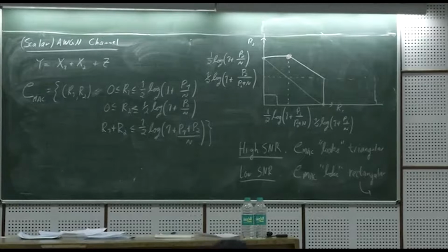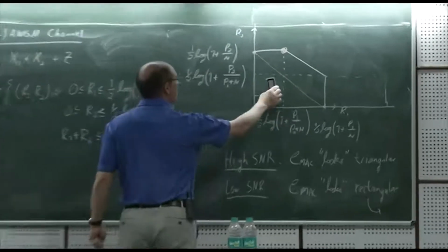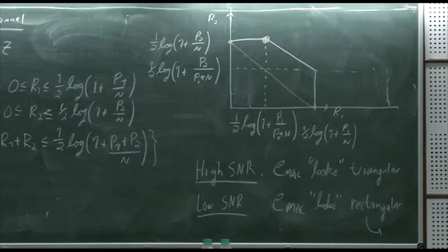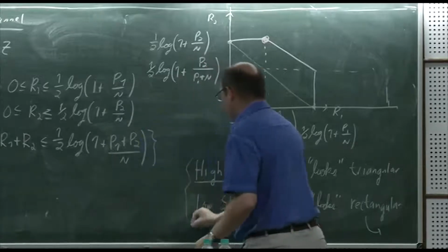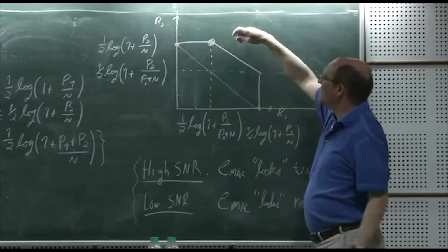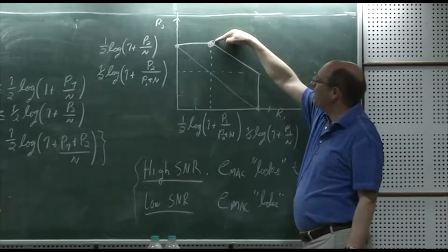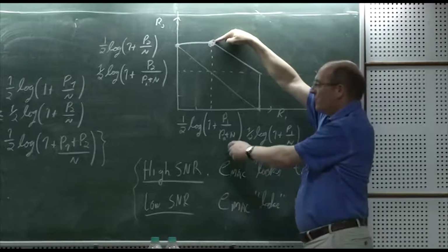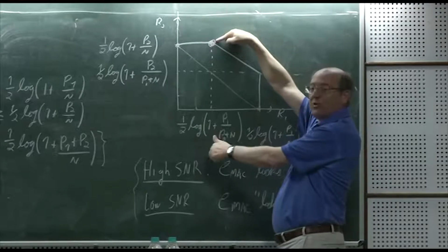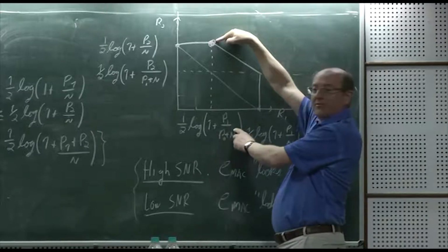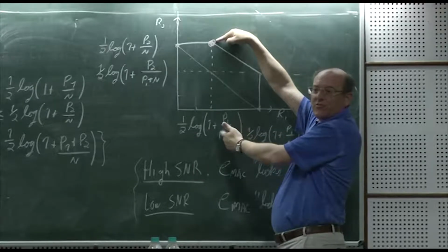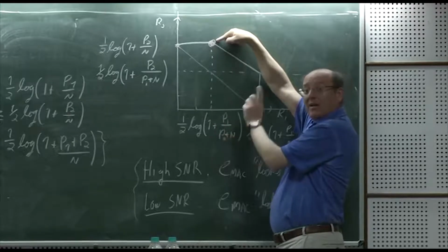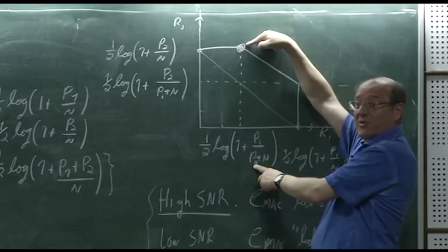Anyway, after all that, I just wanted to mention that first because it's kind of interesting to think about. Let's talk about successive interference cancellation. So going back to the corner points, without talking about how the stuff behaves at different values of P's and N's, let's go back to the corner point. This suggests that user 2 just transmits, and user 1 transmits at a lower rate, and his SNR is this, so it really suggests the receiver should first decode this user by treating the transmission of the other user as noise. Now, the sequence of the other user is not noise, right?